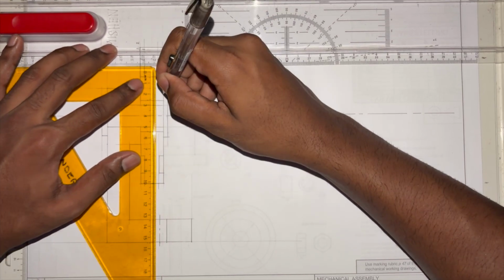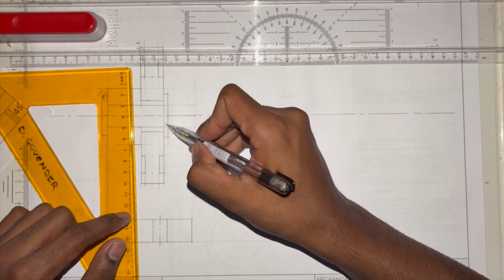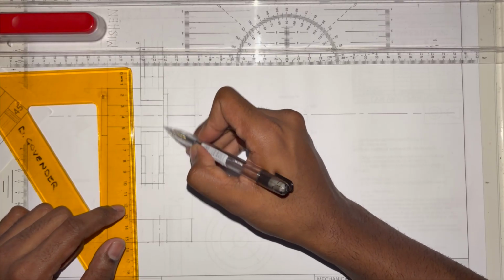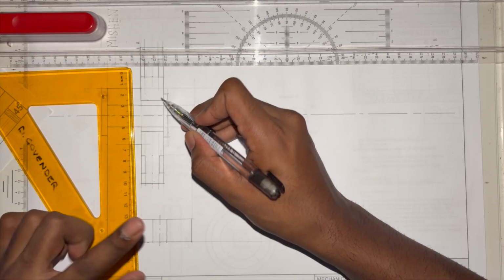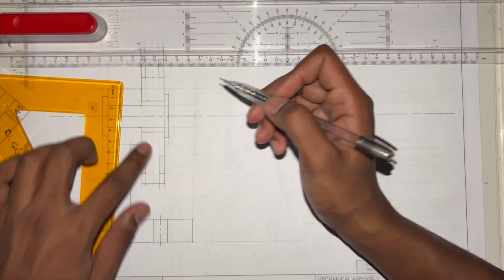So you need to brush up. Okay, we do not cut and hatch a washer. I repeat, we do not cut and hatch a washer. How you see it here is how it's always going to be drawn, like that. We don't even draw the 2 lines of the shaft that go through.